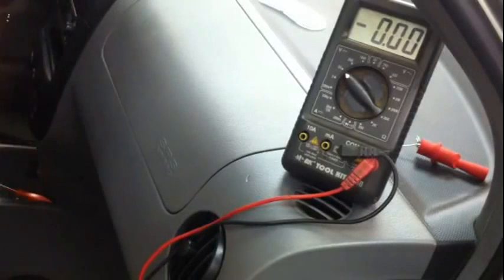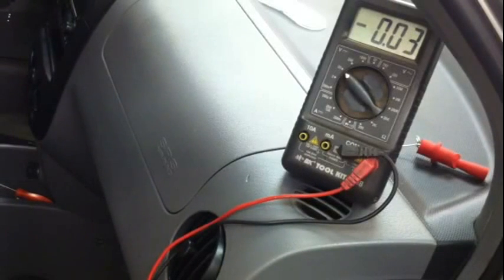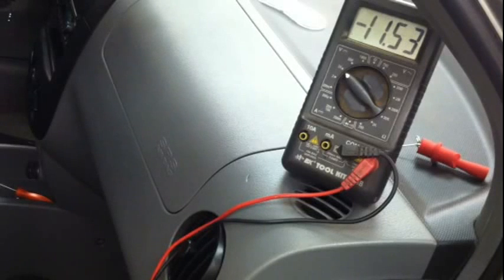Now remember, this will go up, it won't go down, so when I test up, you're going to get a little bit of a higher voltage draw than what you normally should, because the window's all the way up, so it's deadheading the window. So let's see what we got here. Got about less than 1/4 of a volt it's losing. Now if the window was going up, that would be reading 1 or less. So let's go to down. That's the way the window's not working, and see what we get here.